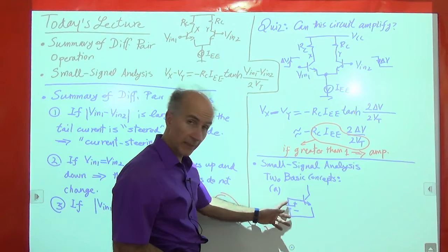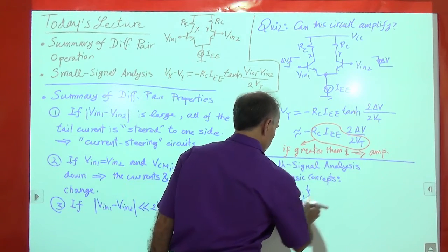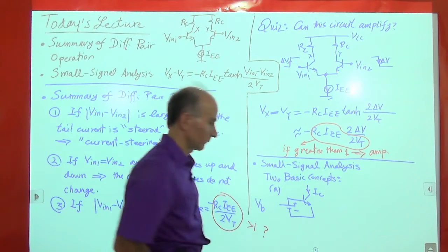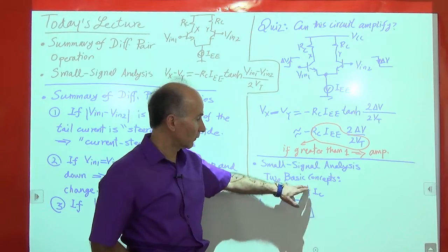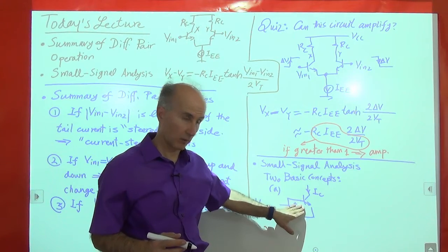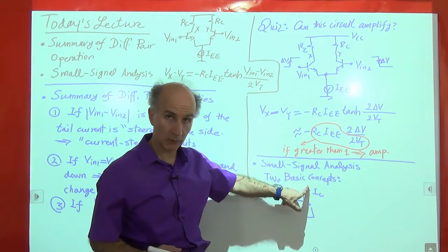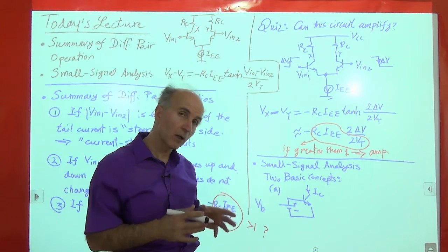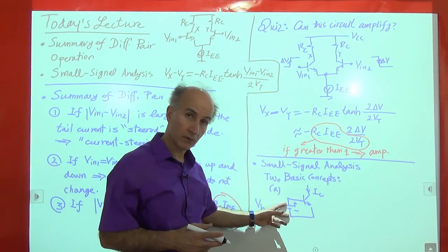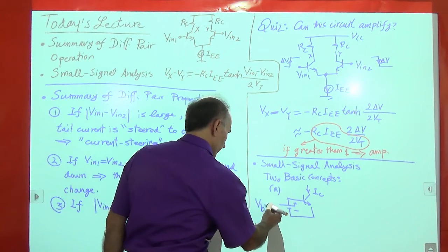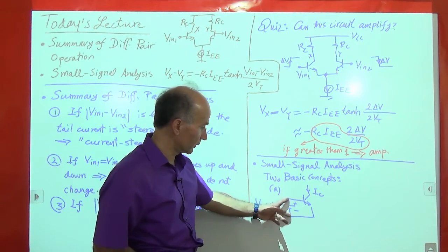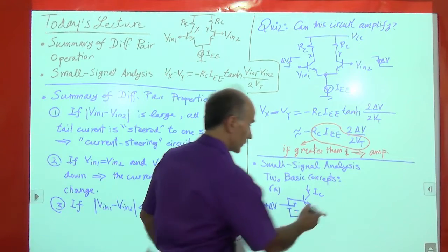It has some proper base emitter voltage and some collector current. So let's call this VB, and let's call this IC. Okay, so apply some voltage, you have some current. This voltage is properly secured somewhere, so the device is in the forward active region. I'm not showing all the circuitry that would be connected here. All right, now I am going to make a small change to the base emitter voltage. So VB will change by some amount, delta V. And as expected, for example, this voltage goes up, this collector current goes up, so there will be a change here.